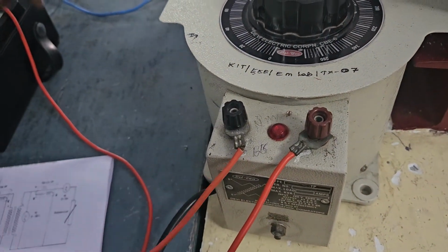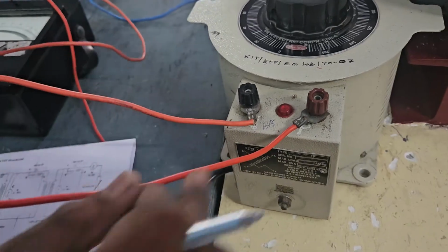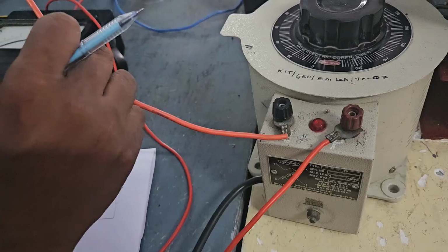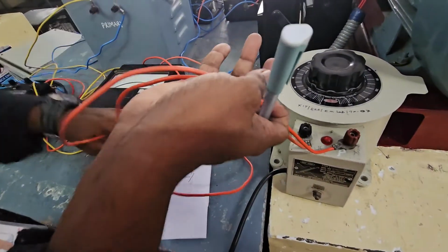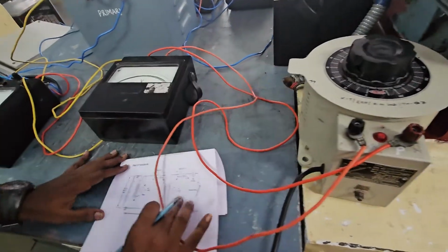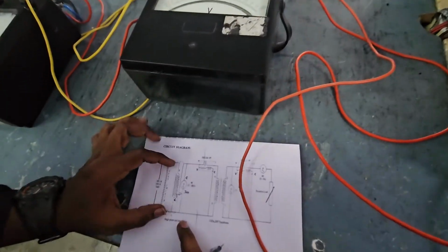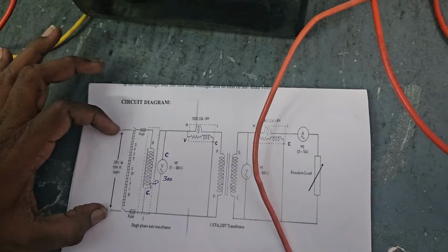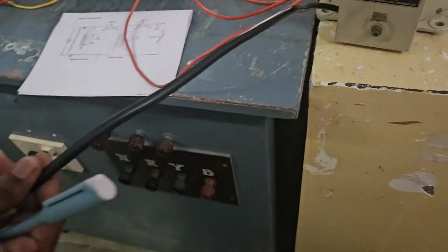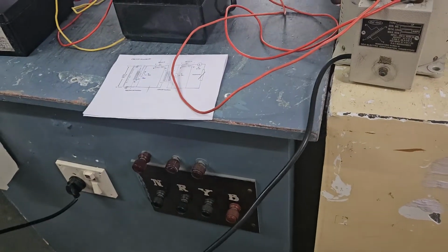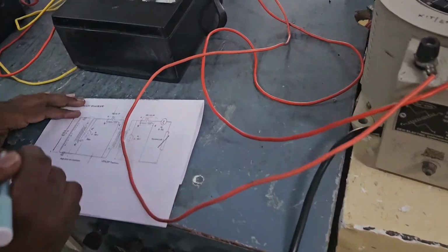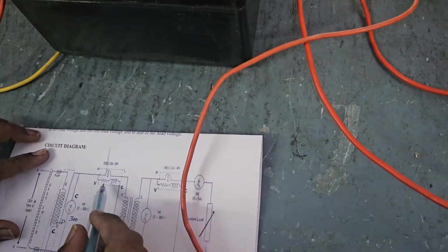So what we did is connect the voltmeter across the auto transformer: phase to common and neutral point to the 300 volt terminal. So we are connected across. Okay, now this is over, and you see the auto transformer input is connected to the supply. This is the input which I connected to the supply side already. Done. Now we'll see how to connect the wattmeter next.